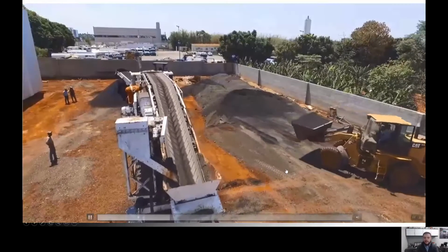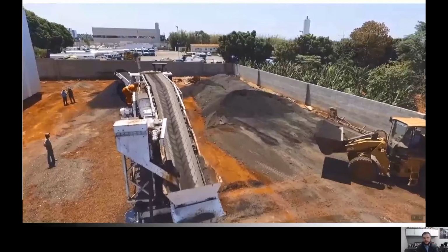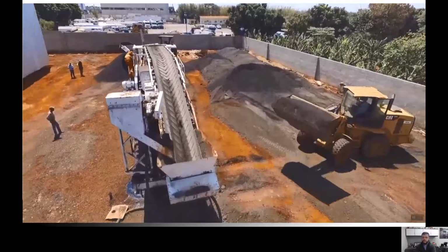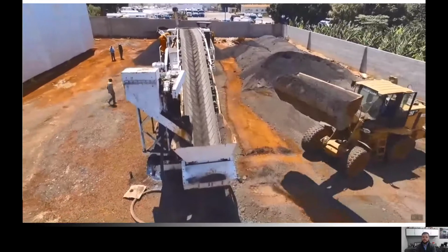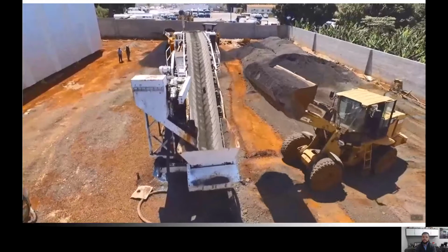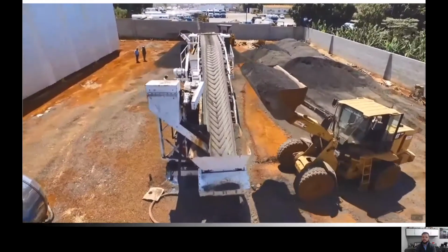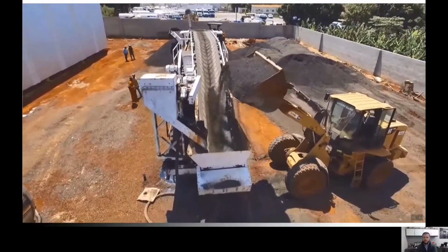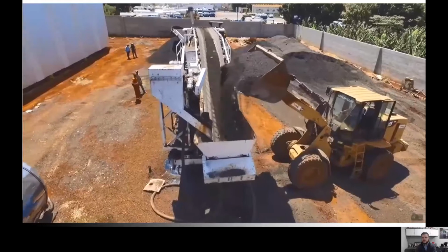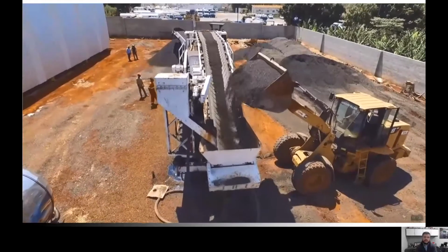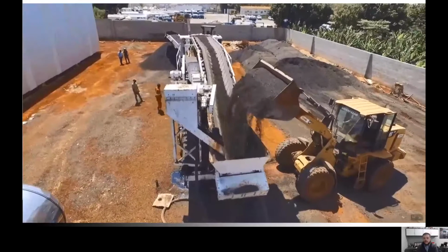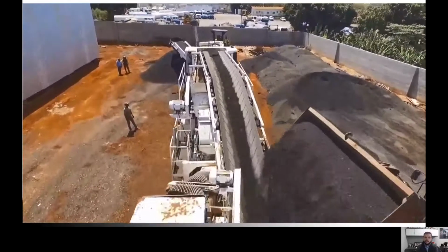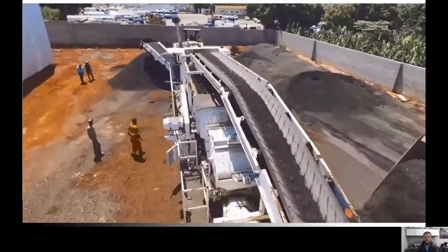Now they're going to keep that RAP on site. This is in Brazil, a little less sophisticated of a process. Normally you'd have a loader or something like that, but on small sites it's a little easier, you can just feed it right onto a conveyor belt. It will then feed into the screen deck, the pug mill, and so on. Basically, you're getting that same sort of cold in place recycled product.